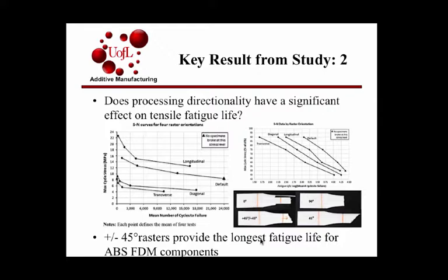They determined that the yielding that occurred during those fatigue cycle tests was delamination between the layers as opposed to the actual ABS fibers yielding under the load. And they plotted the typical fatigue life S-N curve, showing that 24,000 cycles was the best that they got from the default case.